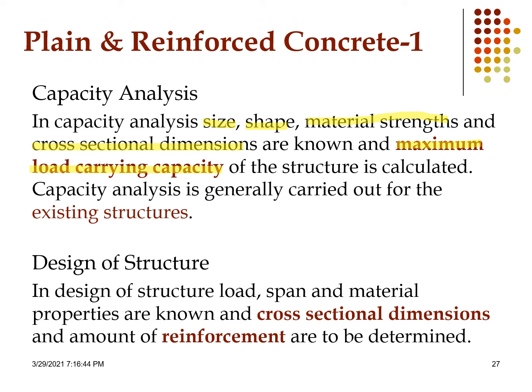If we are given the load, span and material strength and we want to find the cross-sectional dimension and reinforcement in it, that we call design of a structure. I am going to repeat again as this is important. In case of design, we want to know the cross-sectional dimension and reinforcement in it. However, in case of analysis, we want to find the maximum load carrying capacity of the structure.